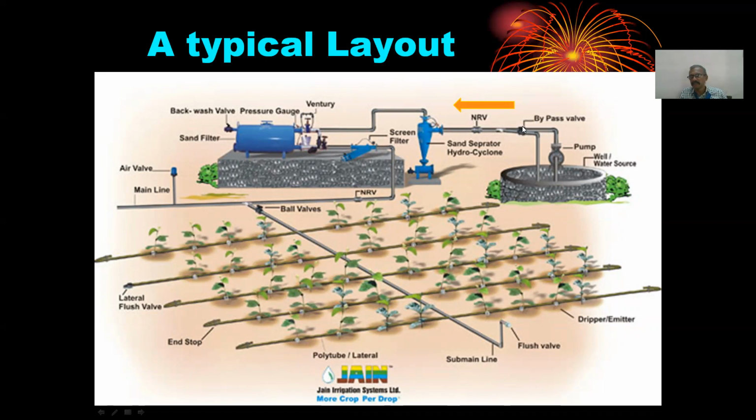When you are using a control valve alone at this side, there is a possibility of increasing the pressure at this side. Increasing pressure does not cause any overloading of the motor. Overloading of the motor, in the sense of electric overloading, does not occur, so the coil burning will not happen.